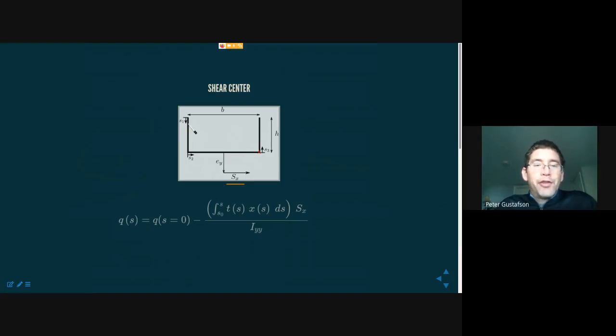As I advised you to do last time, we defined a coordinate system positive downward. So I'm going to draw the resultant force for this segment. I'm going to call that F1. I'm going to draw one this way, F2. Note that the direction is in the same direction as the coordinate system. And here I'm going to draw F3. F1 and F3 are in opposite directions because the coordinate systems themselves, in a global sense, were opposite of each other, although they were defined this way for continuity reasons.